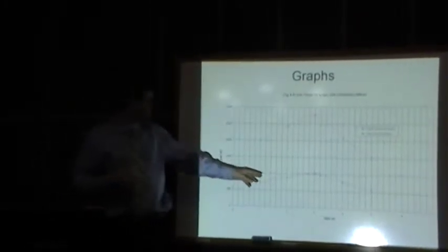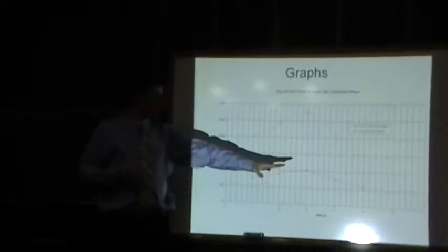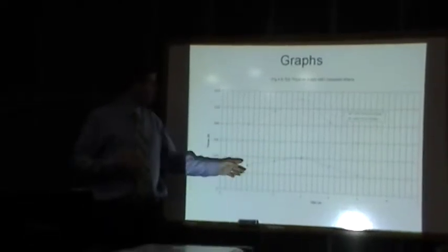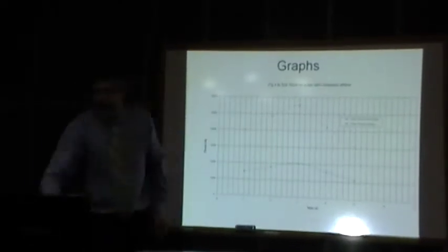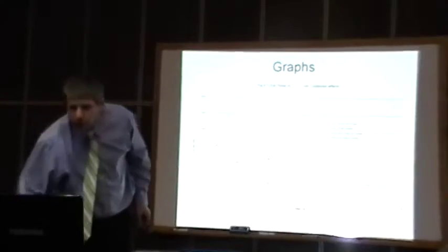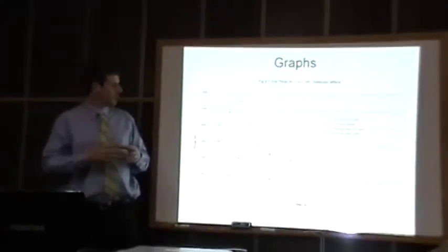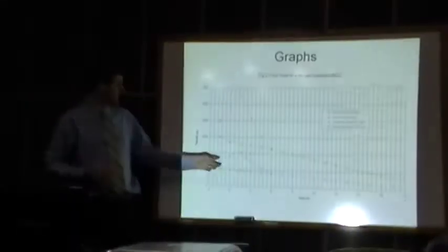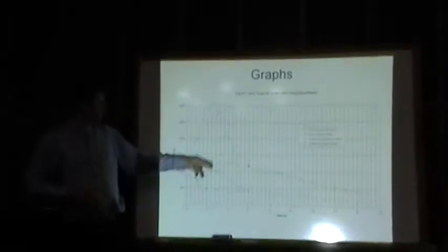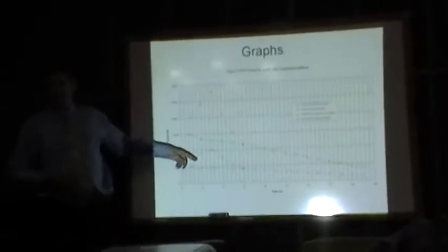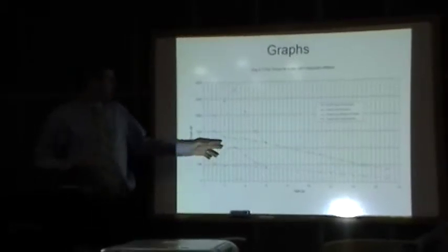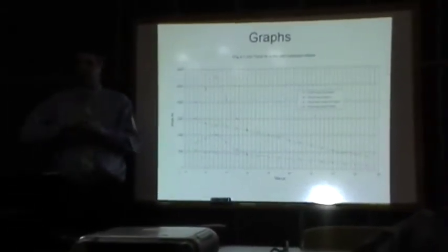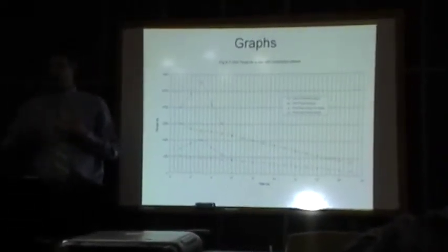This is the exit thrust for the beryllium disk, assuming conduction effects. Now these curves, as you can see, are not gentle curves that essentially trail off. They do have humps in them, and as I graph that in comparison with beryllium where the thermal conductivity is infinite, you still see those. These are artifacts of the theory that I used. I don't think that the theory I used to model the axial conduction is as accurate as it could be.